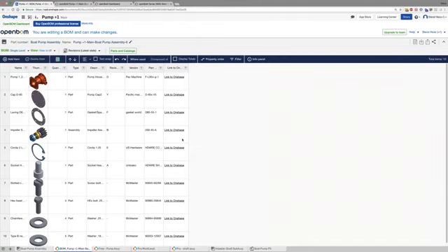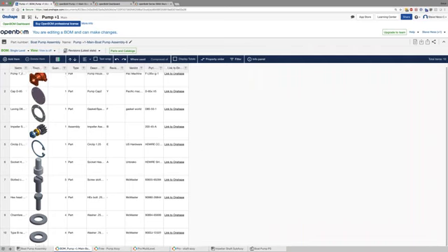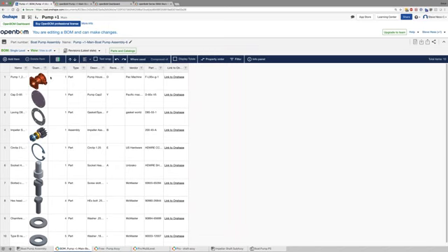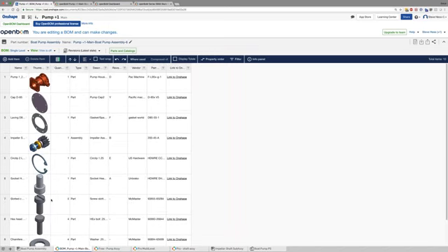This is, as Oleg mentioned, a completely synchronized bill of material that comes right from the Onshape BOM. So let's take a quick look. Some of the things that you'll see here that many people are interested in, of course, are the addition of images. We also keep a link back to the Onshape document. So this becomes a nice index to help you find the Onshape Part Studio where these particular parts are modeled. Some other information we've extracted are, of course, the vendors and other information about the part, its type and quantities, of course.